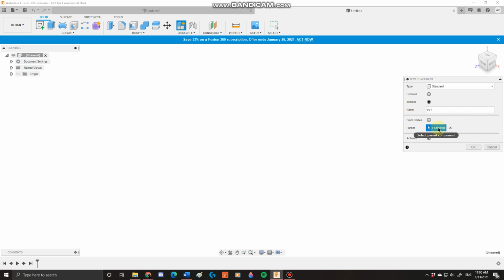The next thing that you want to edit is Parent. Your parent component is what this component logs under. So for right now, we just want it to be an independent component. And to do that, we'll click this X icon here, click this Select button, and click here to log it under our entire workspace. This creates an independent component that does not rely on any other components.